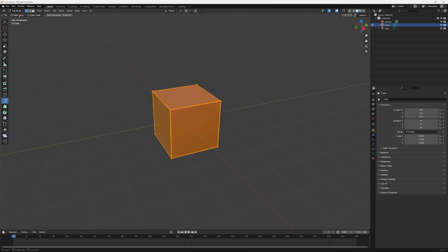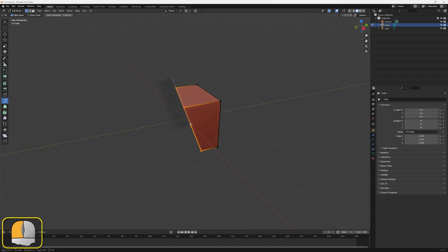If we have chosen to delete one of the two sections of the mesh we are bisecting by checking one of the clear boxes in the top left of the 3D viewport, pressing the F key during the bisect operation will swap which section is deleted.